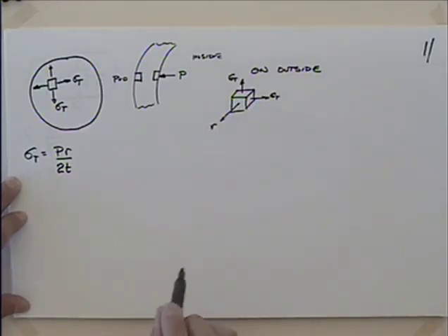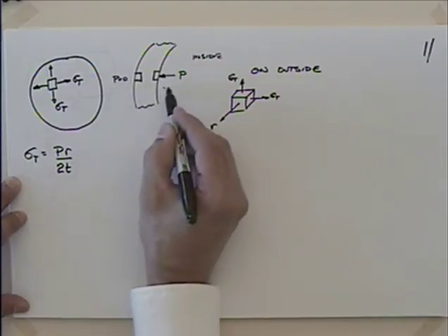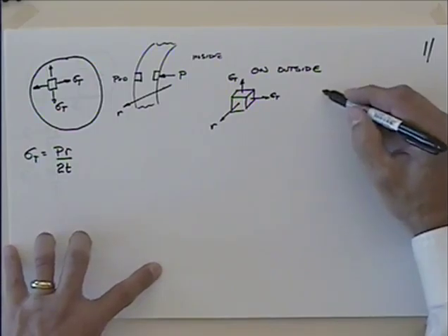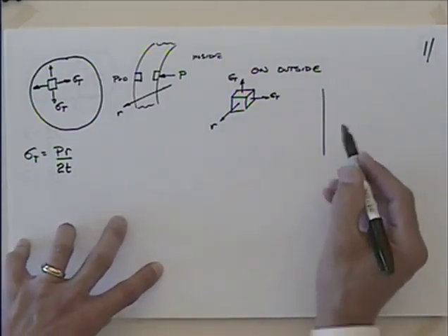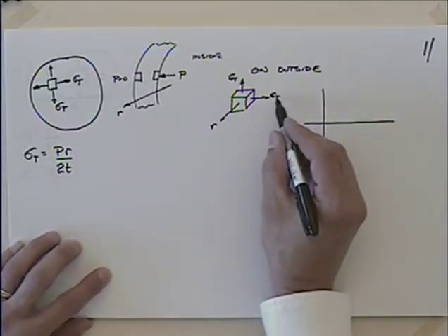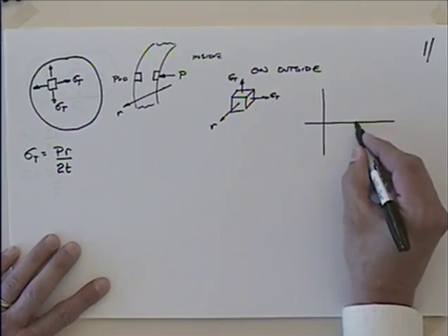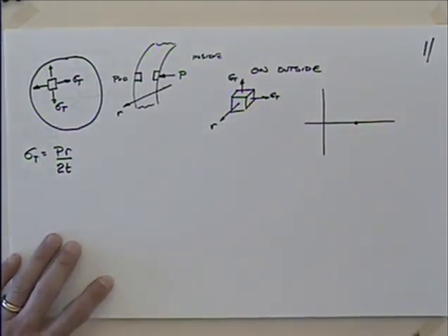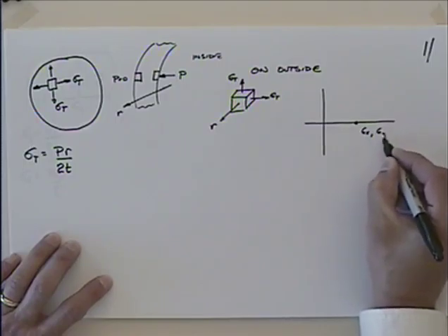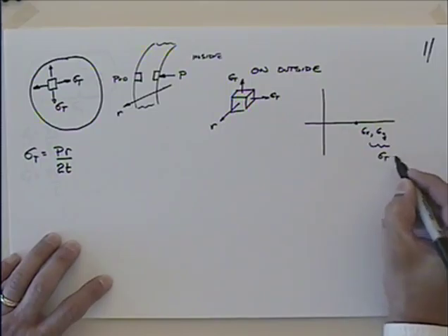I'll just say that that's the radial direction r, radially from the outside. So if I draw a Mohr's circle for this element, these are sigma tangential, those are both the same value, so I would have a really interesting circle right there. There's the xy circle because they're the same value. There's sigma x, there's sigma y, and those are both the tangential value, sigma sub t, the tangential stress.